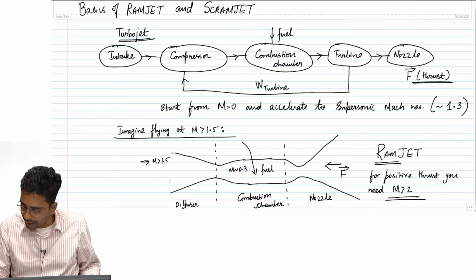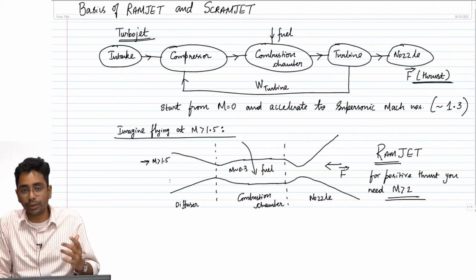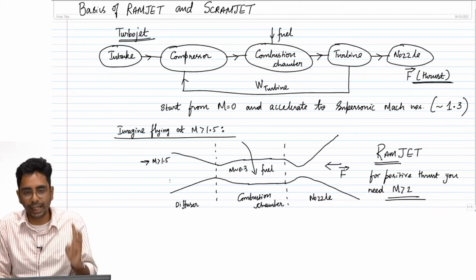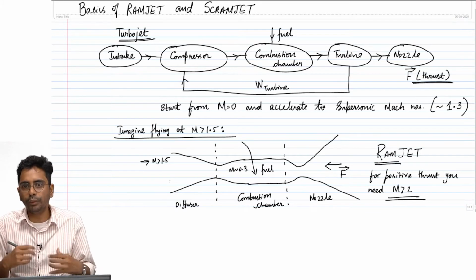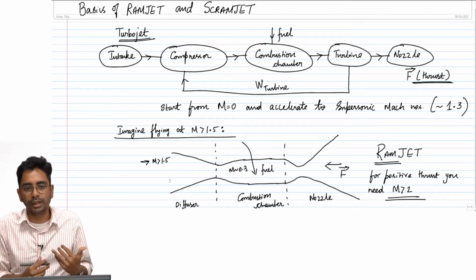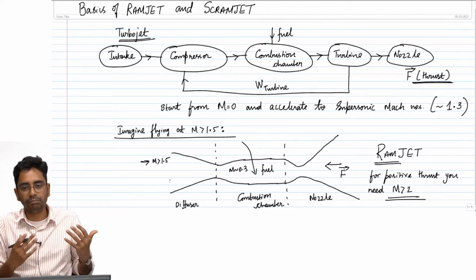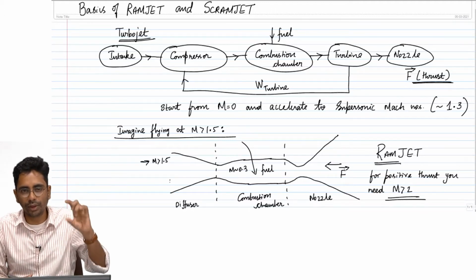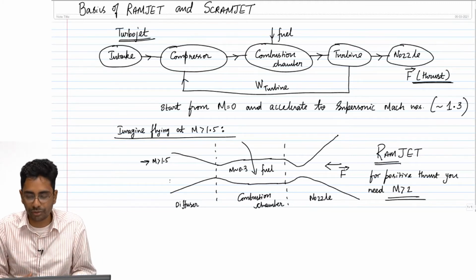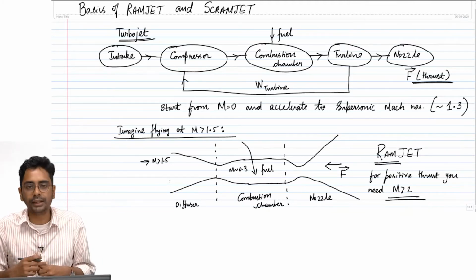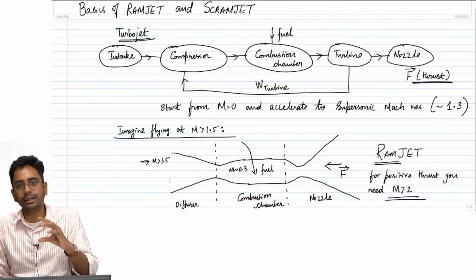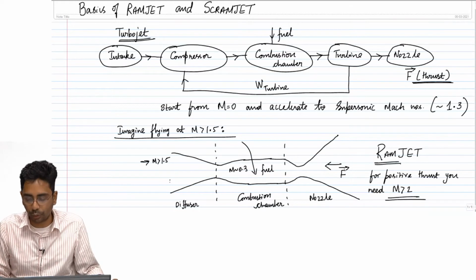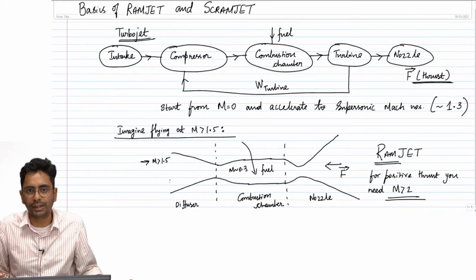There is no net positive thrust till you reach about Mach 2. But now if you are looking at a propulsion device, which could be an aircraft like an SR-71, which had a sort of a hybrid turbojet-ramjet kind of an engine, or weapon systems that you want to fly at very high Mach numbers, you can accelerate these vehicles to Mach 2 and then another simpler ramjet engine can take over, producing thrust, and the engine is extremely simple, at least in principle.